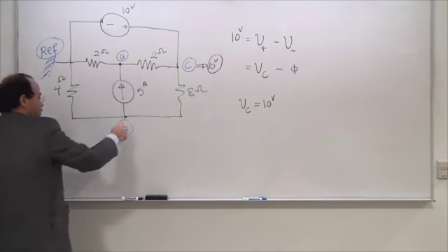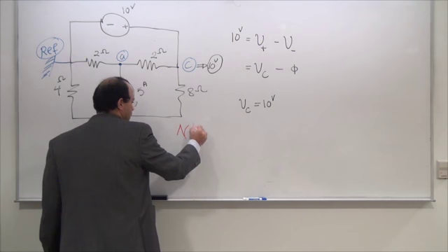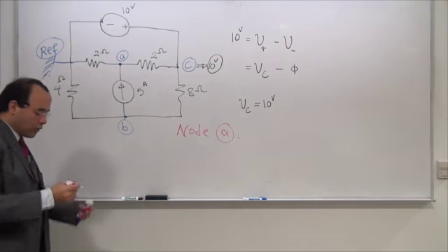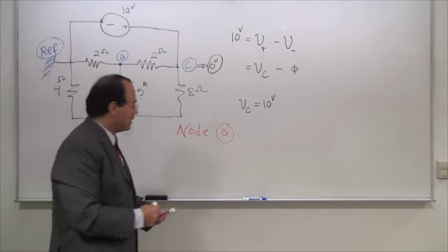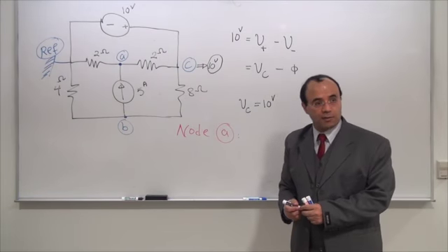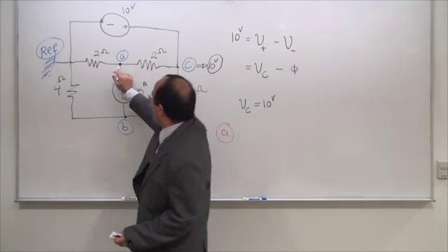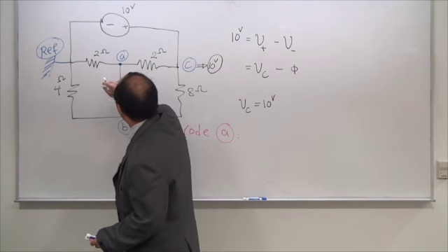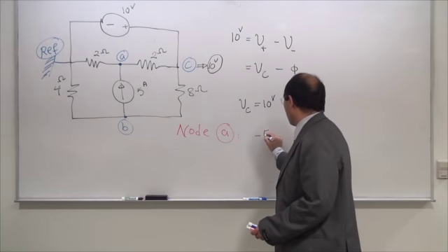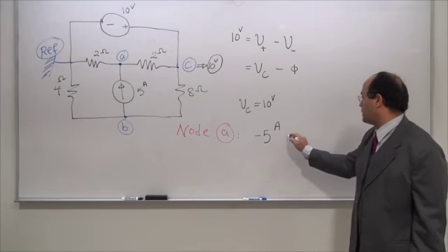So far so good. So what is left? I have two equations to write, A and B. Let's begin with node A. I'm going to make a simple assumption: that this voltage is the biggest voltage of the entire design. When I see A, I see three components, and I'm going to see three terms. The 5 amp source is forcing current into the node, and therefore it's going to be minus 5.